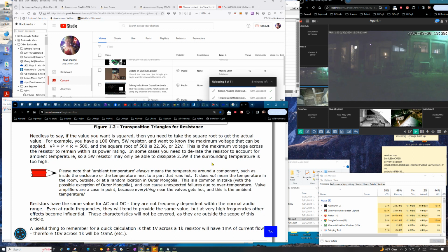But if you think about it, a traditional resistor is going to be mounted on your circuit board. Now the question is what's its orientation? If it's mounted vertically or horizontally or what have you, you need to think about what's taking place for its operating temperature.